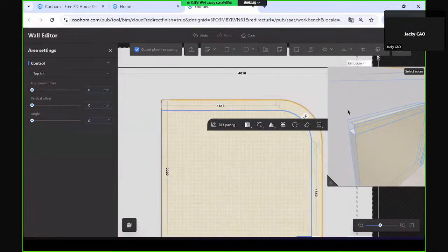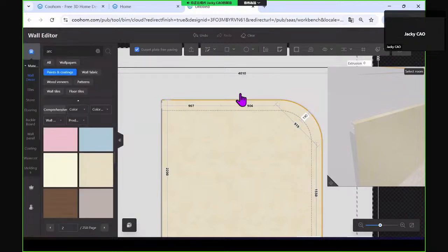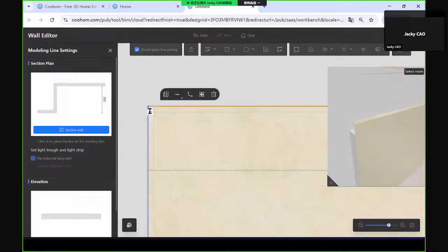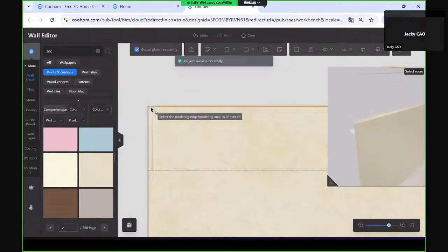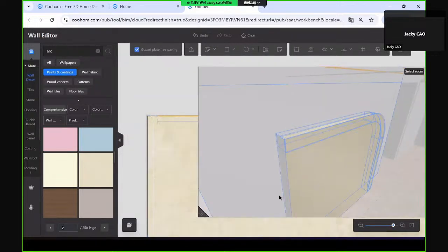For this kind of thing, you just need to directly click the boundary and then use this breakpoint, and you can use this split. Now we have two boundaries, and just pay attention, try to click that dot, this one, let's say giving 10. Just 10, okay, everything, and then duplicate. Duplicate to the boundary and try to let this face turn back.